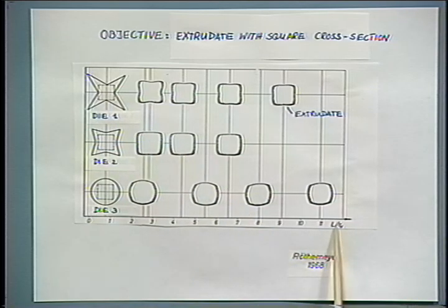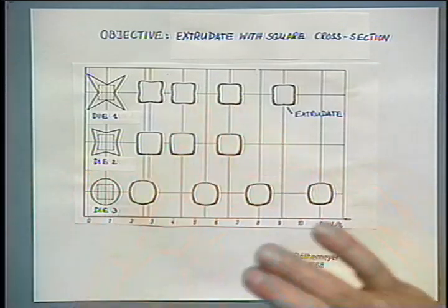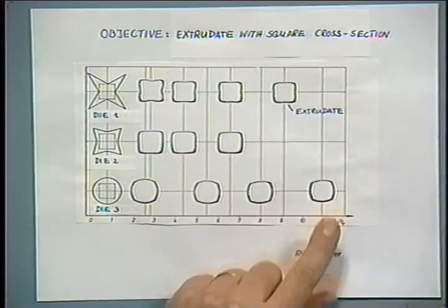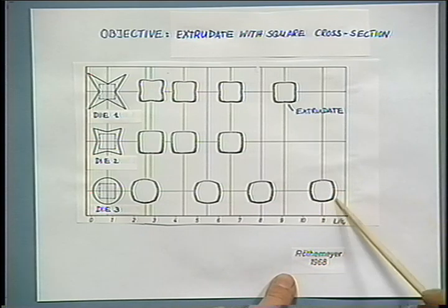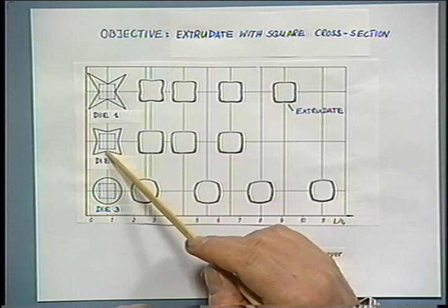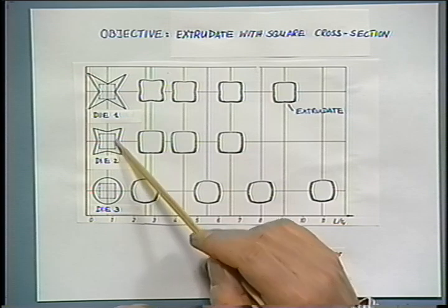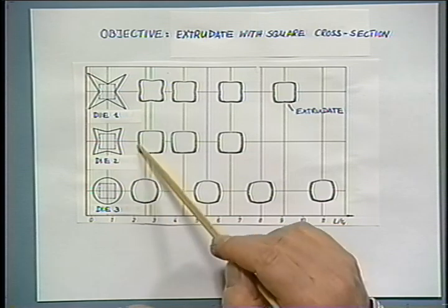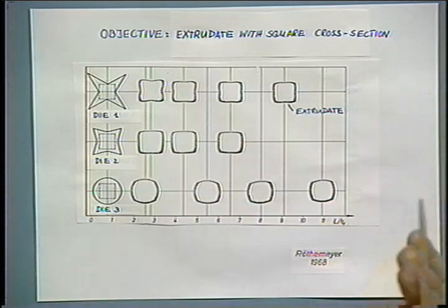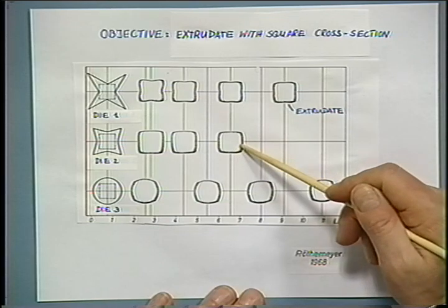Then he made his die of different lengths. And he found that when he extruded from this type of die, a perfectly legal round die, and then a square for quite a while, he gets those balloon-shaped extrudates. They certainly don't qualify for being square. But then by having a pre-section which is helping the corner here, he gets more material into the corner, and it's kind of okay. With a little help, they might be okay.